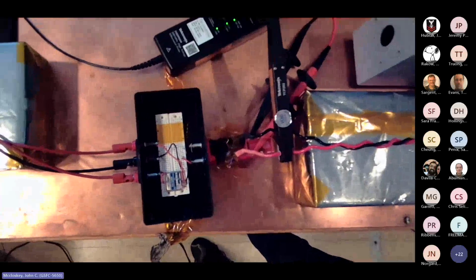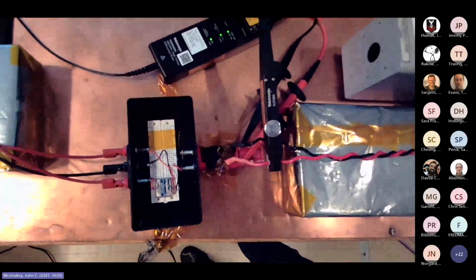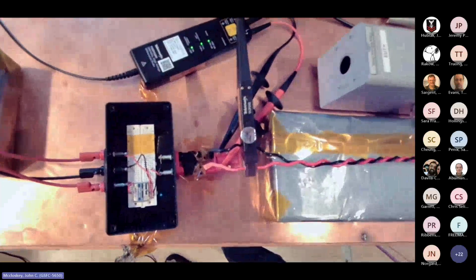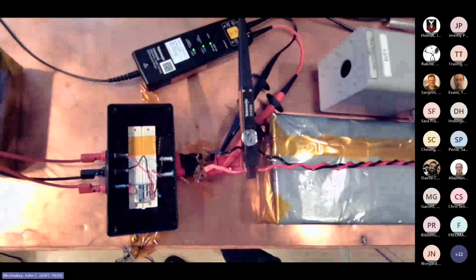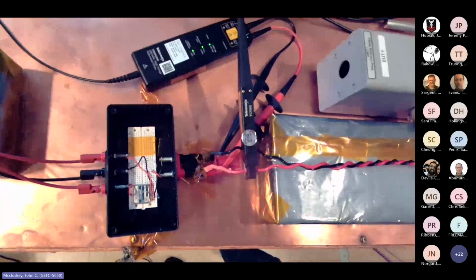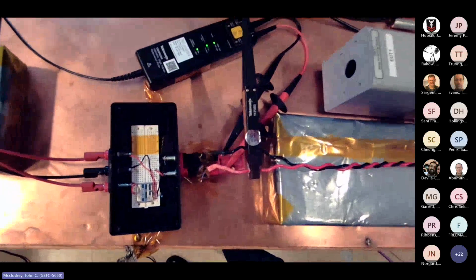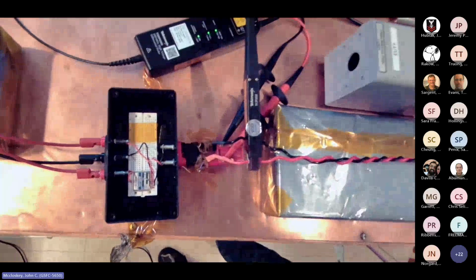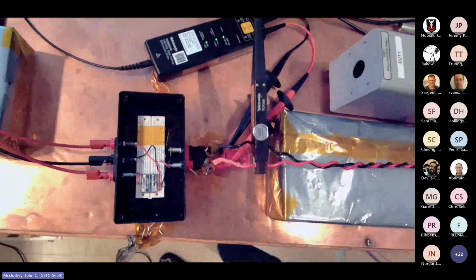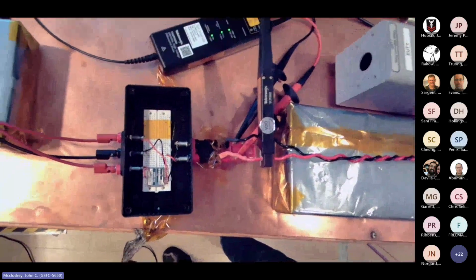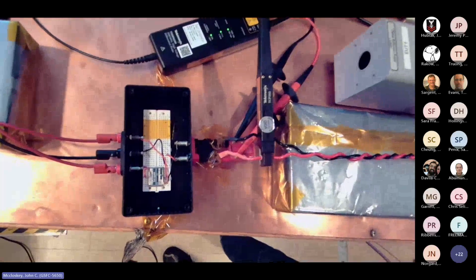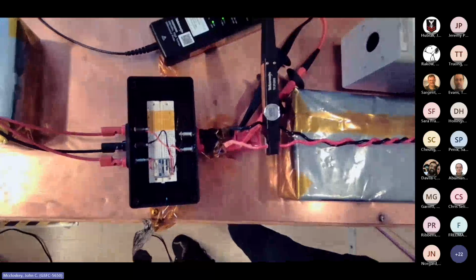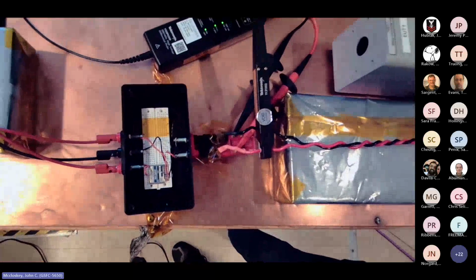Just the nature of how that works is there's a pulse width modulated control signal that's essentially sampling that 28 volt input, and then it adjusts the pulse width accordingly to control the output voltages within the desired range. You can look on the data sheet. I have the data sheet available, but it's going to give you plus minus 15 volts plus or minus whatever they specify. But it's an inherently noisy process.